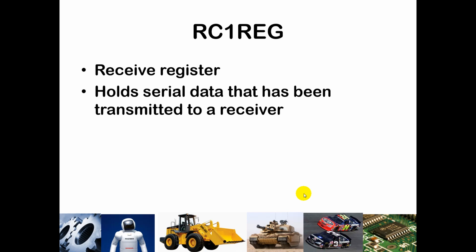RC1REG is where you will actually receive the data back. So on the receive end, that will be where the data will come in, and that will be held until you pull it back out and put it into a variable of your choosing. And so that will be very important to use as you are on the receive end.